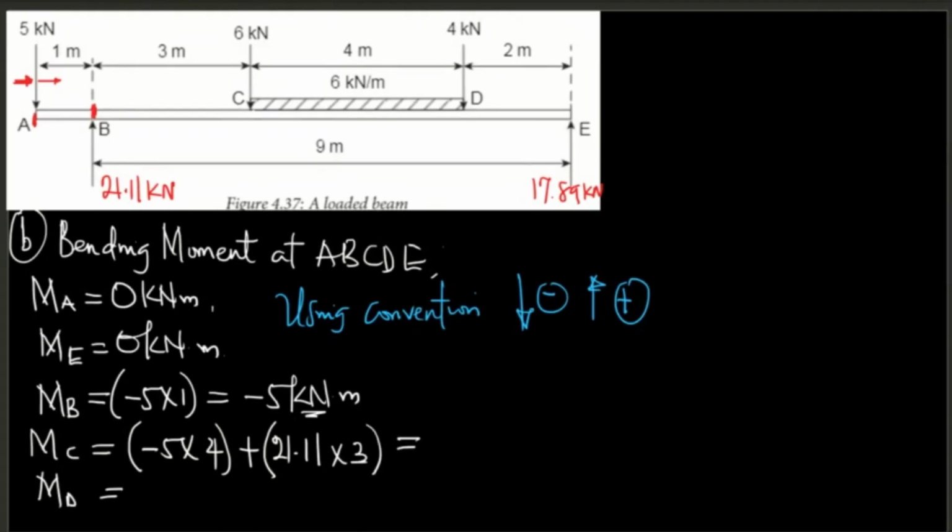The bending moment at D, I'm going to walk from the right to that section because it's going to be much easier.